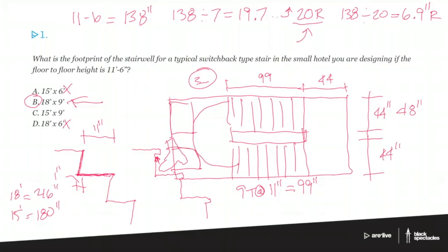So yeah, other issues here. The travel path you could imagine being an issue. The railings, you'll note that railings always go beyond the risers. They go a foot past on either side, including getting the angle full down to the correct height. So the footpath can actually often be close to 2 feet past by the time you have the angle going. Those kinds of little issues are things you should know in order to be able to answer simple questions like this.